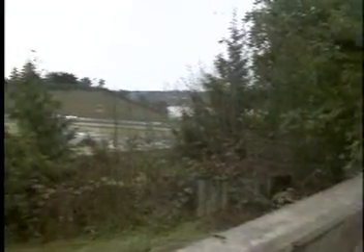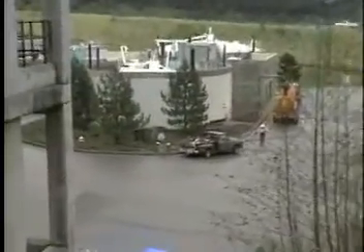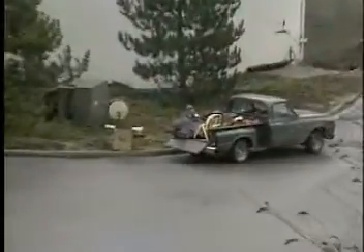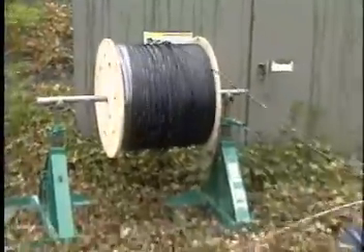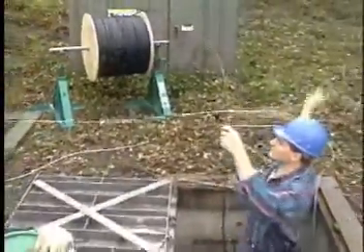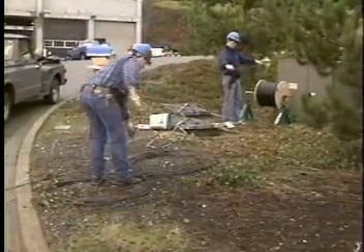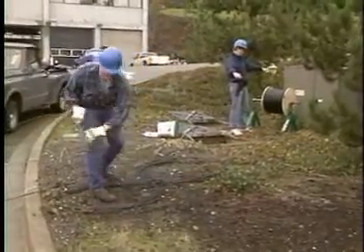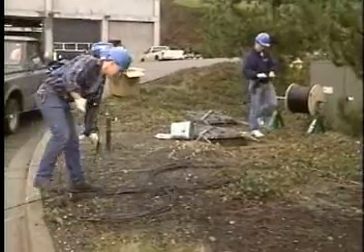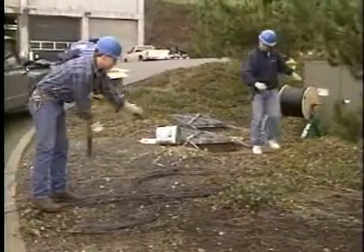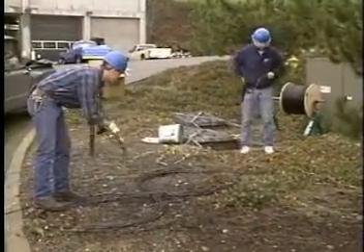Center pulling of fiber optic cable is recommended for long-distance runs. From the midpoint of the span, the cable is pulled from the reel in one direction. After pulling through an amount of slack cable, the remaining cable is spooled off the reel onto a figure-8 pattern on the ground. The cable is then pulled in the other direction to the end of the span.